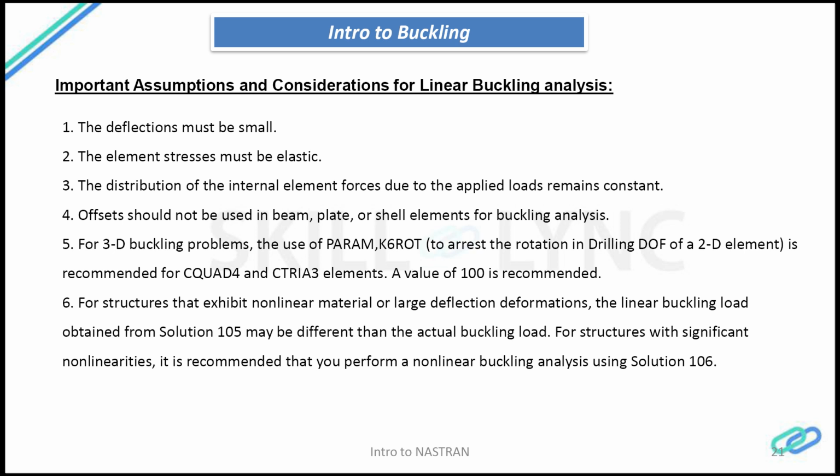Before you submit the job, or before you create the PDF file, you should make the offset 0. Otherwise Patran gives some errors in the F06 file and it doesn't solve the problem. So you should keep that in mind.